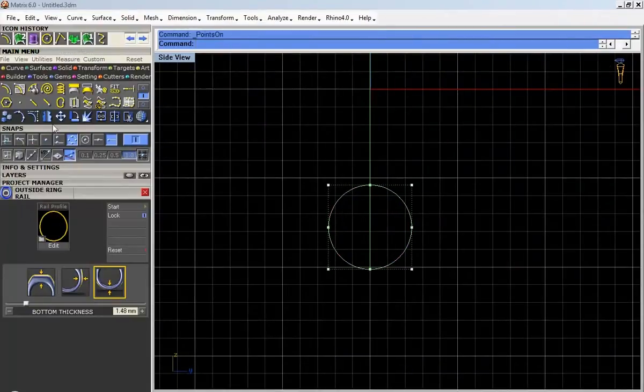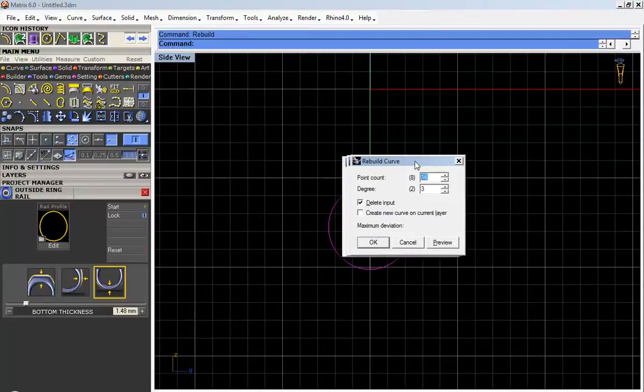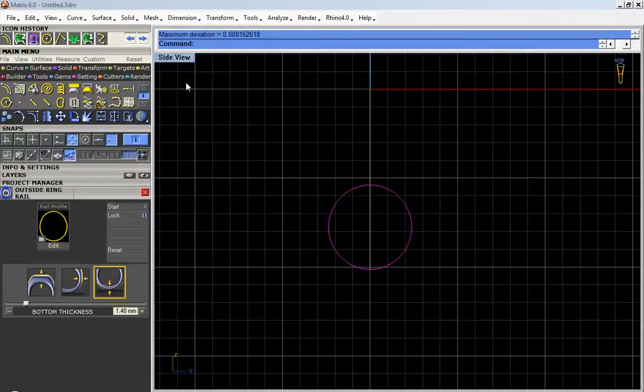I didn't rebuild this curve. Alright, I need to rebuild this also, so I don't get them into pieces when I explode them. So as I said always, if there is a smooth surface, the degree should be 3. It was 2, so I made a mistake, so I'm going to rebuild this now. Okay, I'm going to do the sweep 2 again.